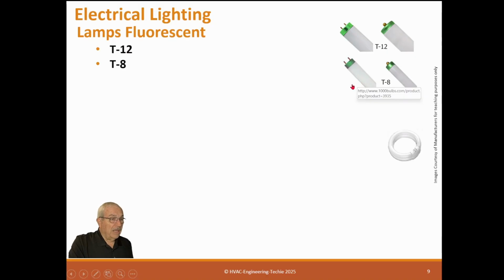So we did a lot of lighting retrofits going from T12 to T8 because you only had to change the bulbs. You didn't normally have to change the ballast. And then there was T5s, and T5s was a big step to get more of the same. They wanted to do the same thing they did going from T12 to T8 by saving energy going to T5, and they did, but it didn't actually catch on. There's a lot of T5 fixtures, but nothing like going to T8s.